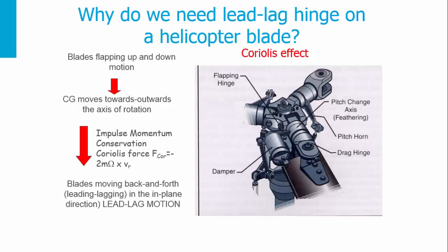This is why, in order to avoid the hunting of the blades, so the motion in the plane of the rotor, we need to introduce a lead lag hinge.